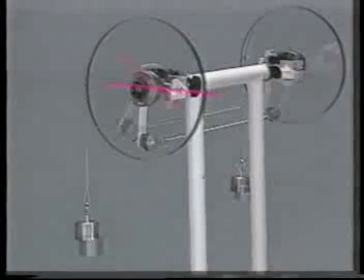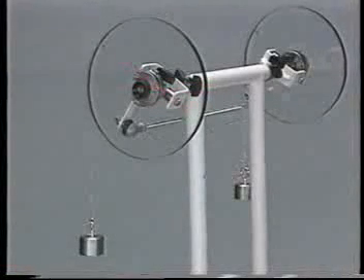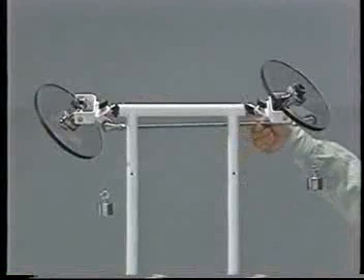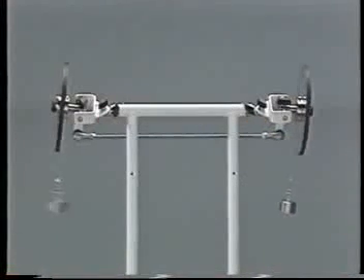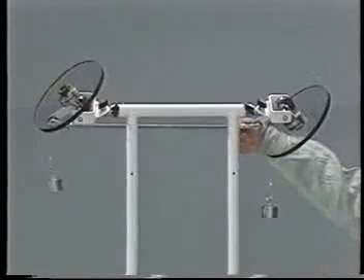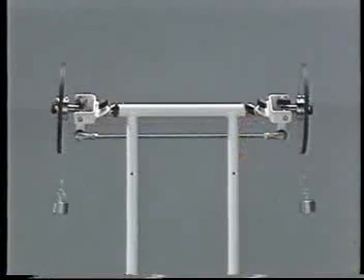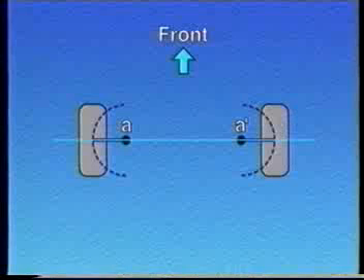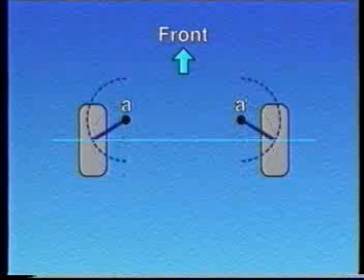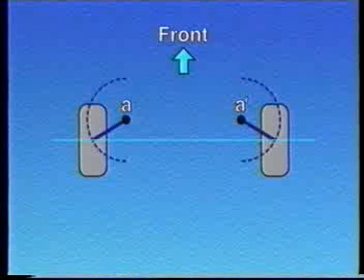Now a caster angle is introduced. Let's turn the wheel to the left in the same way as before. As you can see, the left and right wheels swivel back to their original straight-ahead condition automatically. This figure demonstrates that the points A and A' where the extension of the steering axis intersects the ground shift forward by the amount of caster trail because the caster is applied.